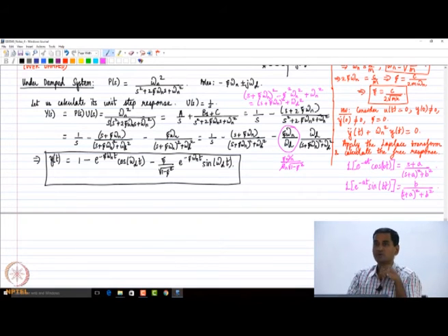Okay. So immediately we can see that the expression which we derived is the unit step response of the underdamped second order system, right? And we can immediately see that it has two exponential terms. The exponential terms have the real part as the exponent. You can immediately observe that. Of course, in general, you can write cos omega d t and sin omega d t using Euler's relationship, and then you will see that the poles will be the exponent. That also is something you can do. So that is observation number one.